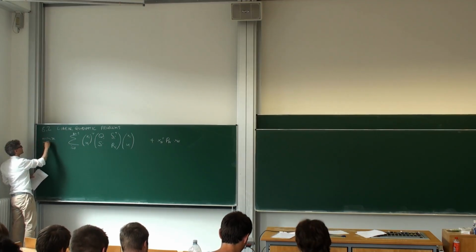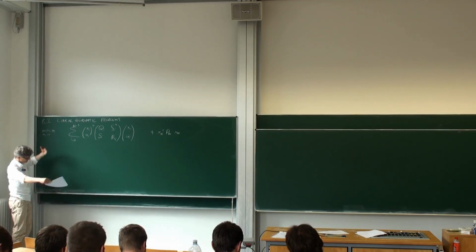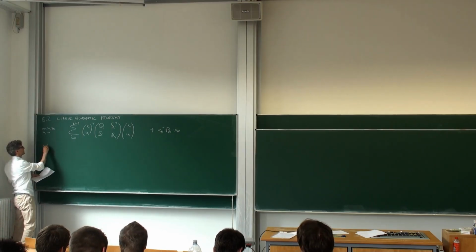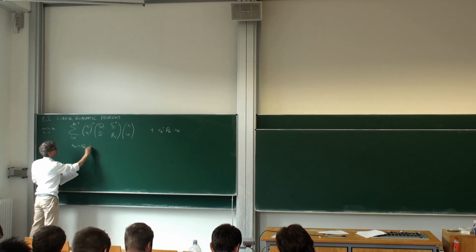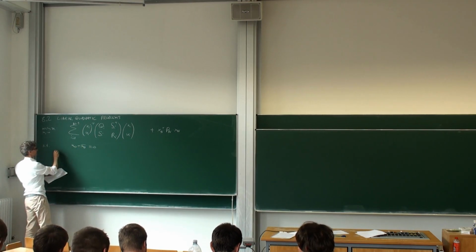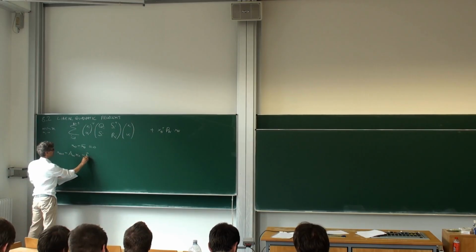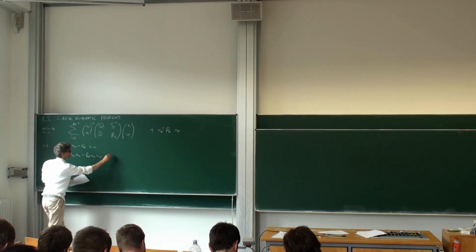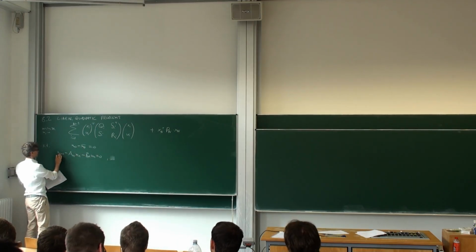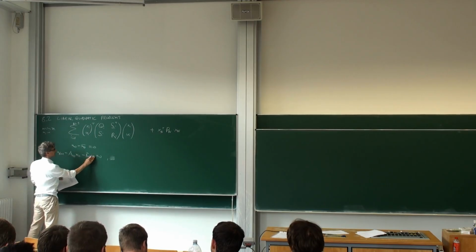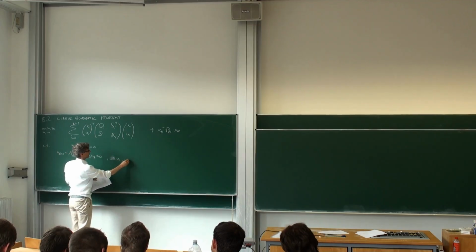We will minimize it over all state and control trajectories. I will just denote it by x and u in small letters, but it's the concatenation of all components, just to make it simple. And then our constraints are x_0 minus x_0 bar equal to 0, a matter of taste how I write them. And here I have x_{i+1} minus A_i x_i minus B_i u_i equals 0 for i. Oh, sorry, this should be an i, everything is an i. i goes from 0 to n minus 1.